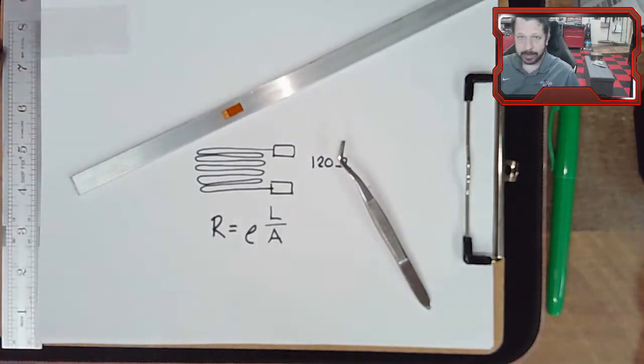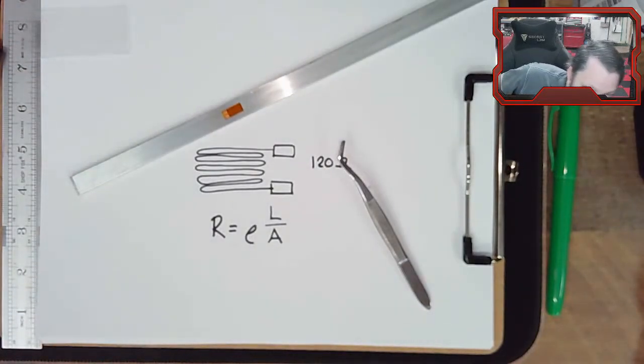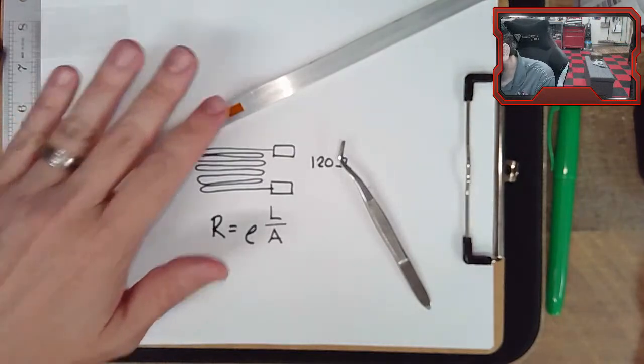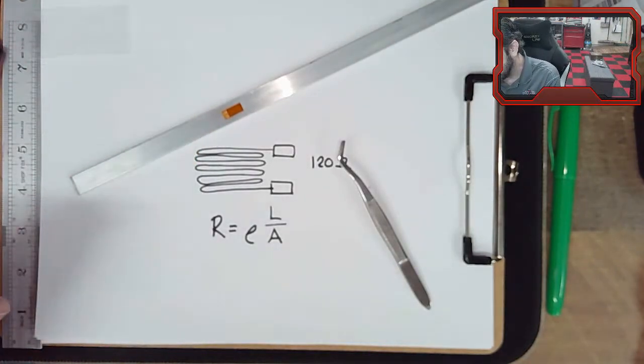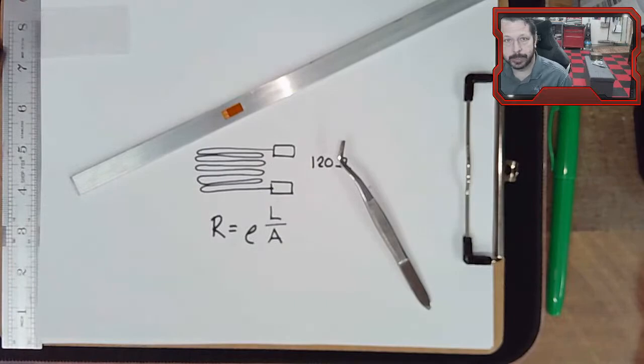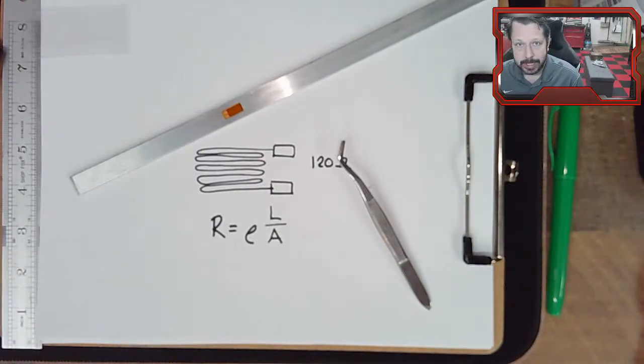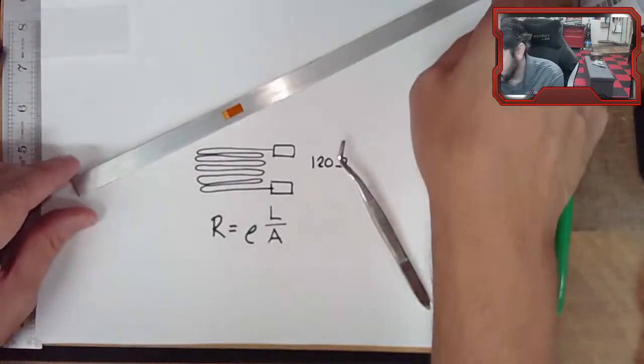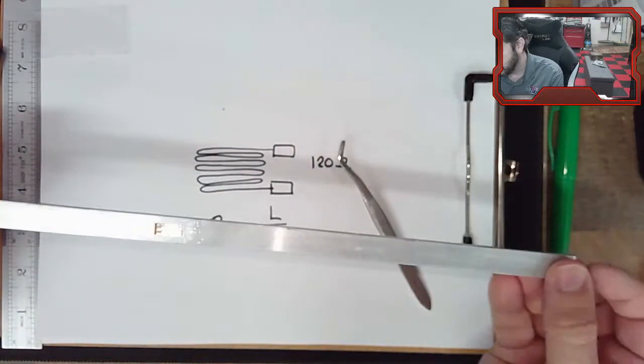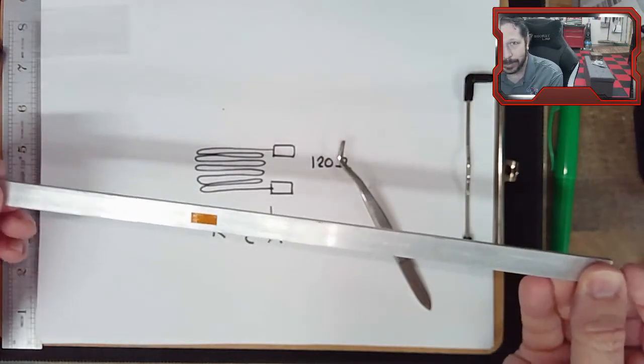So now we've mounted it, and that's one of the key parts, because we want this strain gauge to experience the same strain that the beam is experiencing. Because if we can figure out the strain in the beam, then we can use beam deflection equations to back out what the force that created that strain must have been, assuming we know things about the geometry of the beam and the material. This is 6061 aluminum.